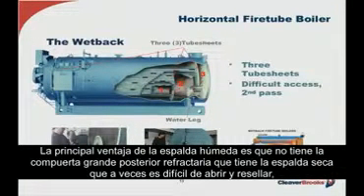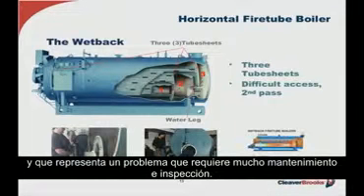The main advantage of the wetback, of course, is the elimination of the heavy rear refractory-filled door found on the dryback, which is sometimes cumbersome to open and reseal, and is an ongoing inspection and possible maintenance issue as well.